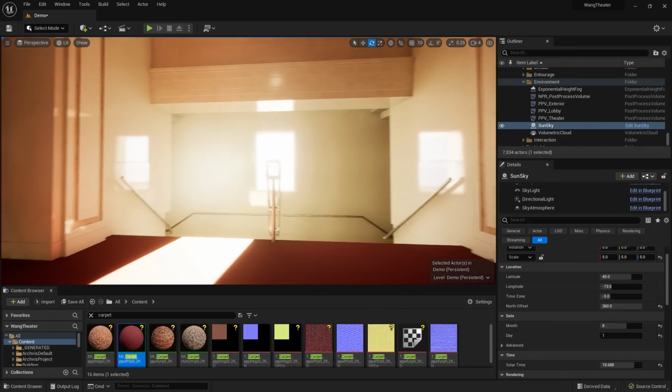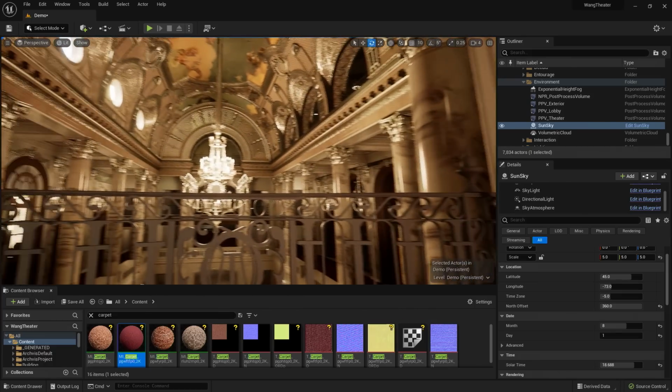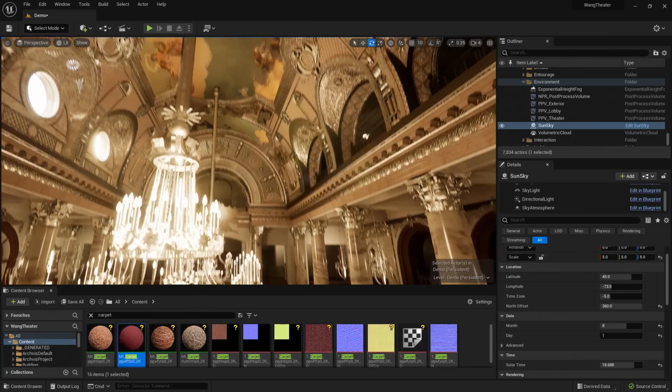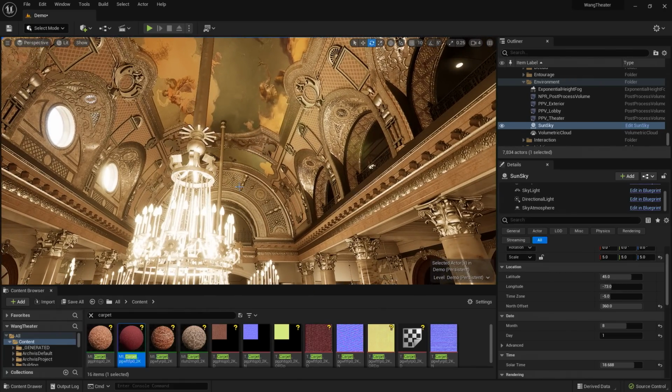Now you're also able to use emissive materials as well. So as you can see, here we do have some emissive materials that are going into the light calculation. Now there is a limit to how many emissive objects you can have before noise artifacts begin to appear. So it's advisable to not fully rely on emissive materials, but placing light sources nearby can provide an additional boost of light when needed. So now I've gone into a little bit about how I built out the project.